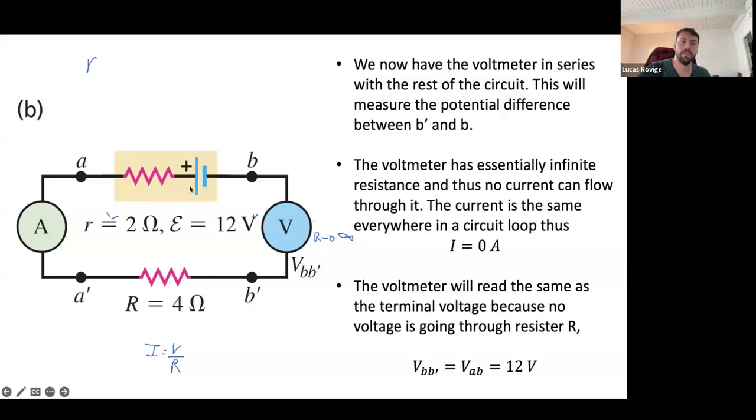So it can have its use, for instance, if you want to measure the EMF of your battery. If you look at your system without any current flowing, then you access the EMF of your battery. And it doesn't matter what the internal resistance or outside resistance in your system are, because no current is flowing through them. And so there's no potential drop associated with the current.